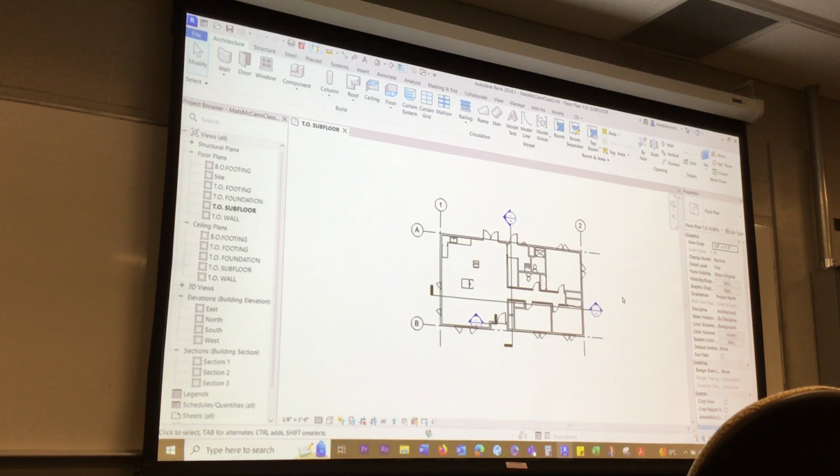The exterior pitch of the vault is 12:4. We'll make the inside 12:3, or 3:12, however you want to say it. It could be 3:5. They're scissor trusses. They're thick at the top, and then they come down to a heel where they're skinnier, like little arrows. So the first thing I want to do is create a gable roof with a 2-foot overhang. We're going to use 4:12.